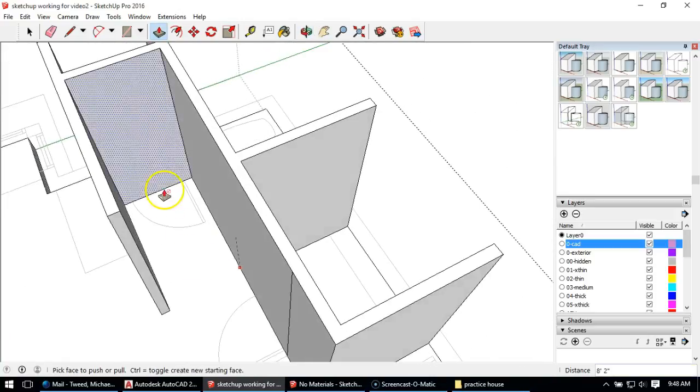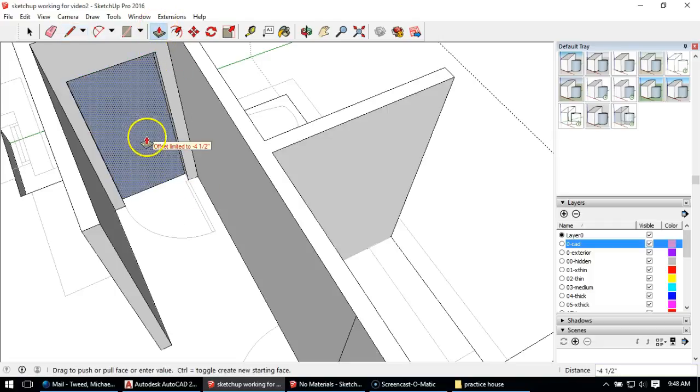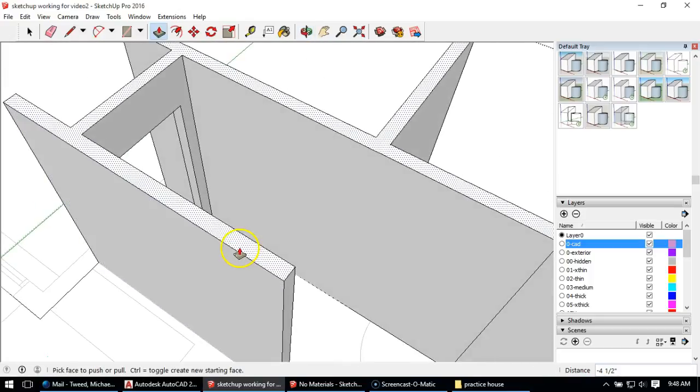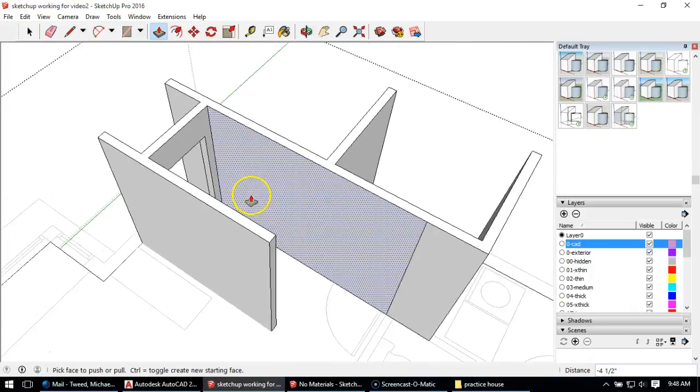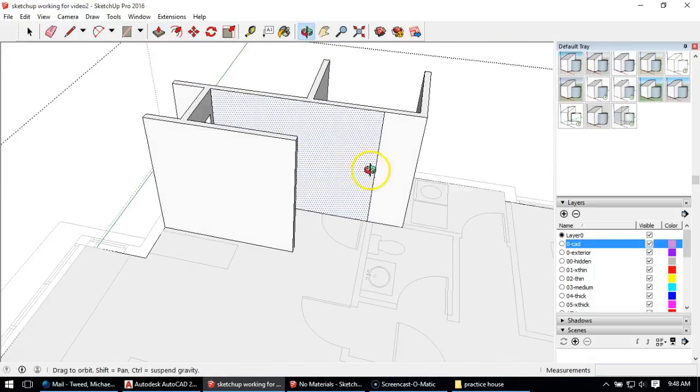And then I can come back and I can find where my doors are, and I can just come in and draw a line up and say, okay, well, my interior doors, they could be 7 foot, they could be 6 foot 8. So I'll just draw up the height on each side just because I can see the door. I can just type in height on each side. I can cross the top, and then I can push-pull that right through the surface to create the door. Of course, you could go and add trim to all these things if you wanted to. I'm not going to. I don't think that level of detail is really going to be seen in the model.